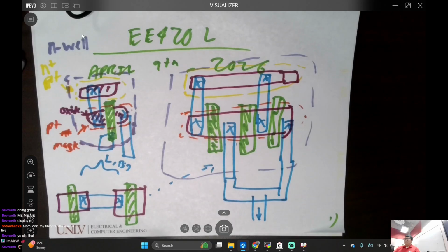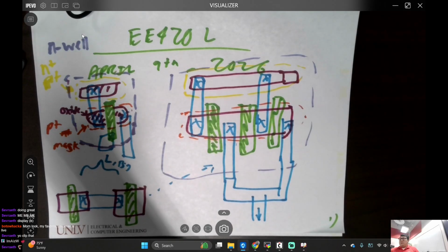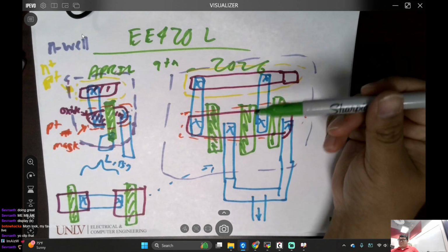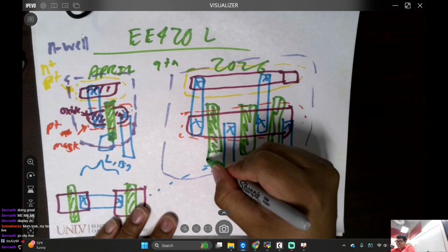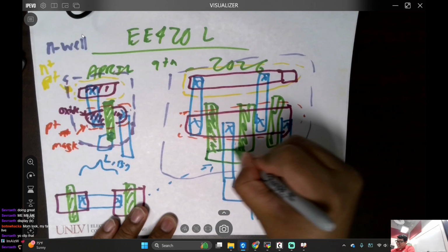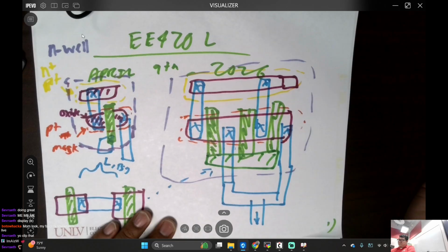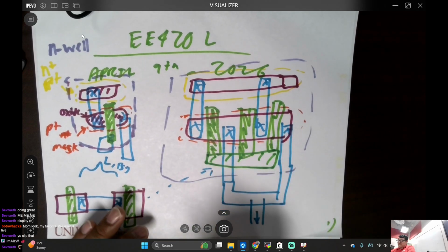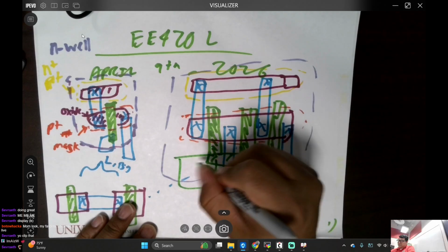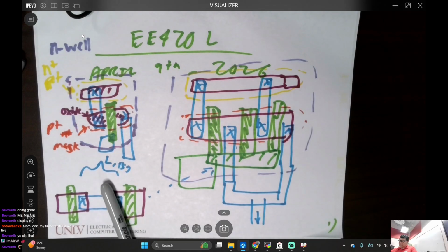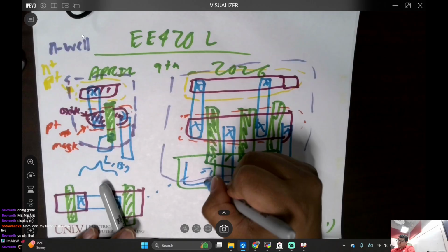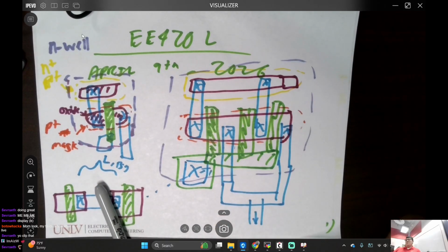How about the gates? There's a weird trick you can do as an engineer. And remember, poly is a wire. Poly's a wire. You can do this. Is that cool? And now I have a place to escape. And then I can put this big tap right here, and then I can have a blue layer right here. Boom, escaped.